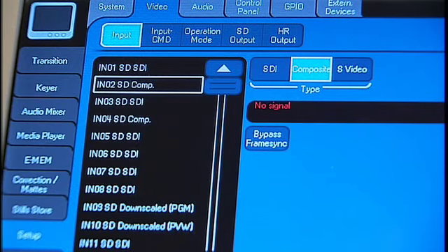Sources 9 and 10 can be set up to downscale the high-res inputs. The high-res inputs are at the bottom of the list. When you set up the high-res inputs, one of the options is to scale up SD inputs. This menu allows you to determine how you want to adapt between 16:9 and 4:3 inputs.